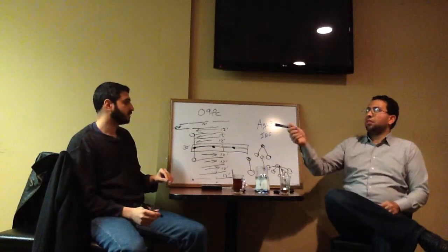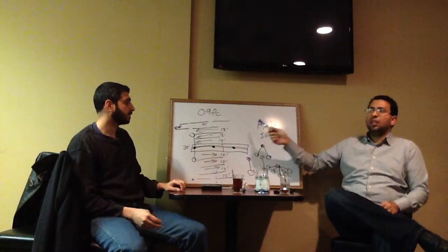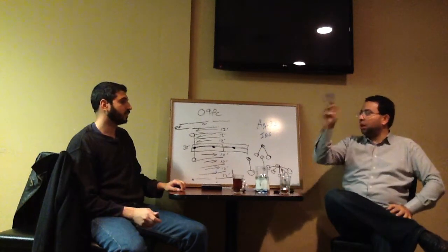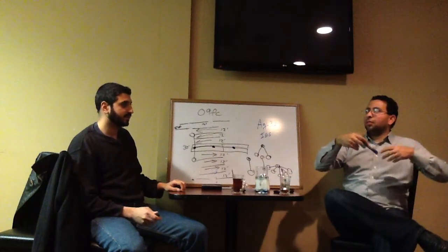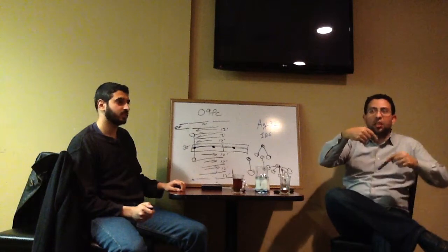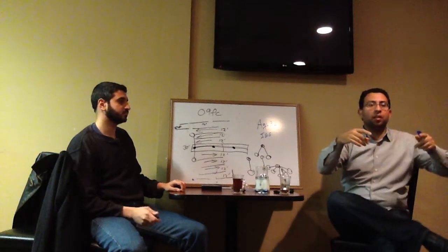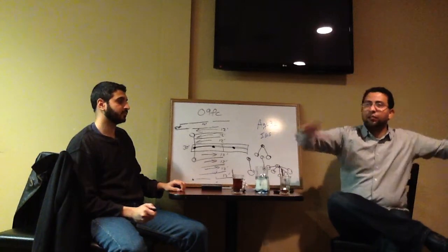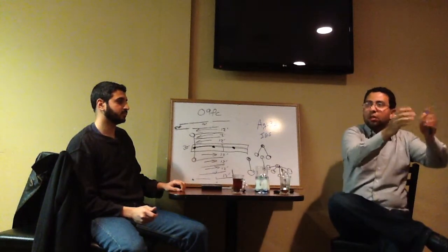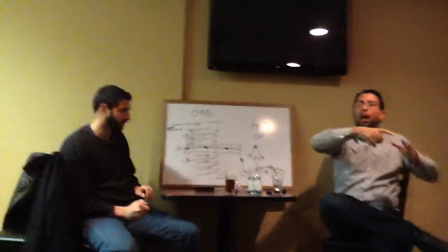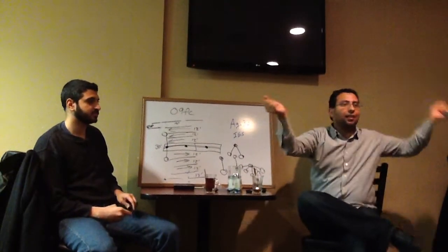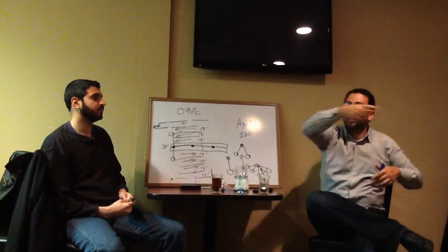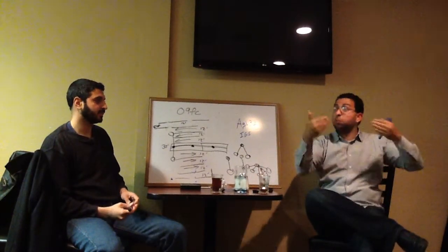And this is another thing, maybe if you can touch base on the different light patterns, the R2, the R1. The light pattern itself. Sometimes, let's say you're doing a sidewalk, you don't want the light to go right and left, you want it just to focus on the street. There is R1, I believe. R2 is going to the right and left. Let's say you want something to consider the back, you go with R3. It shoots more to the back too.